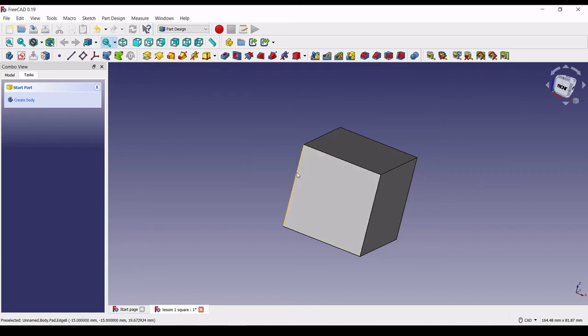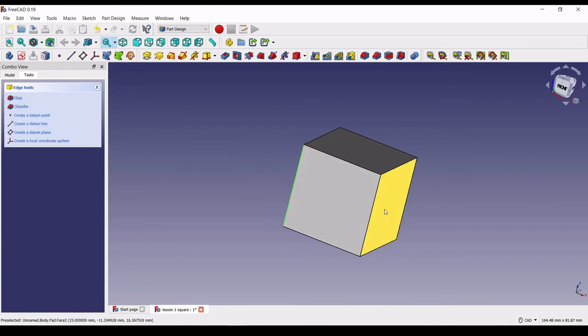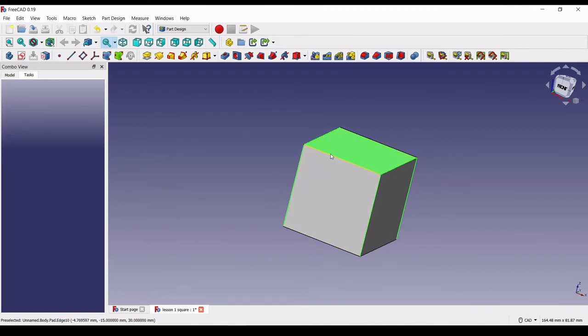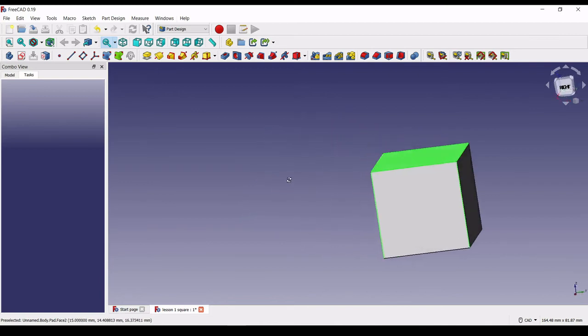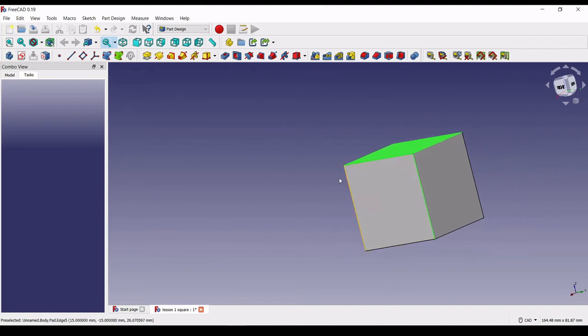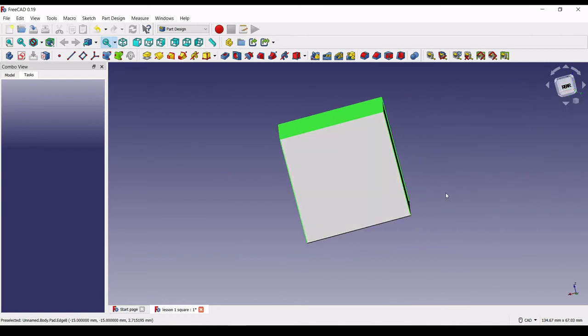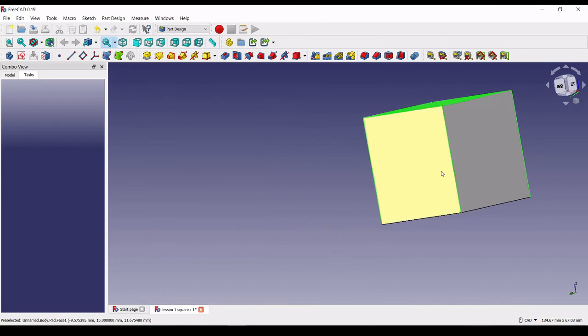But first you need to click on the side, press Ctrl and choose all the sides that you want to make round. So you'll see it changes to yellow for each one that you have chosen, and you can move it over. Now this one takes a little bit of practice to do all of these. So when it's out of the right, just click and drag and pan it back until you can find all the edges. Just make sure that you did click all the edges.